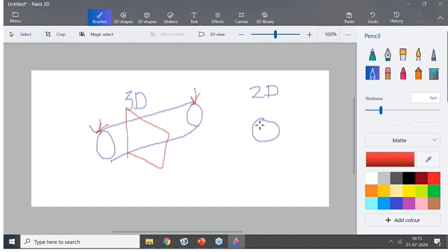Having said that, there are a lot of advantages of doing 2D modeling. If you can take such kind of advantages, for example, the number of mesh elements reduces drastically, and it also helps you to compute very quickly with approximately good results. But again, yes, that is an approximation.